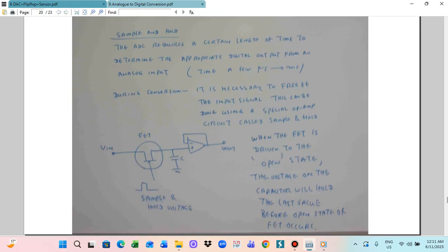The sample and hold circuit consists of a capacitor. When the capacitor is charged, it stores the energy, so the electric charge relevant to the input signal can be stored in the capacitor. The sample and hold circuit is utilized in the input signal system. In this data acquisition system we can utilize an 8-bit binary number, which can be transferred within 2 microseconds.